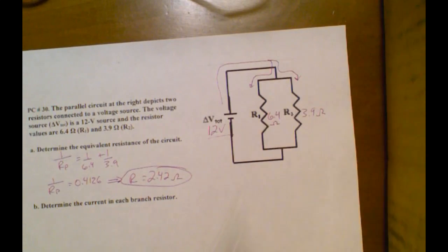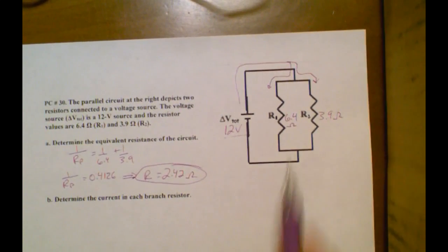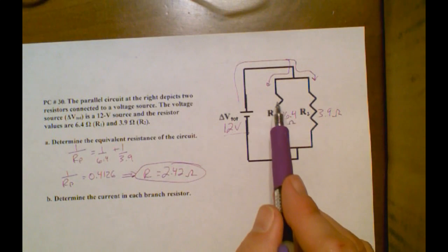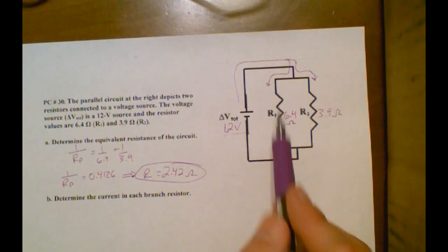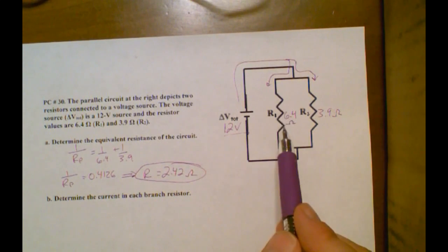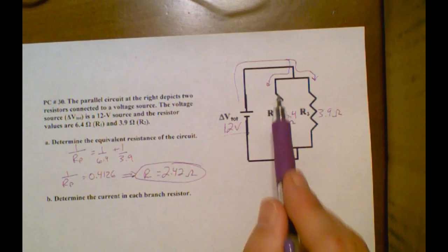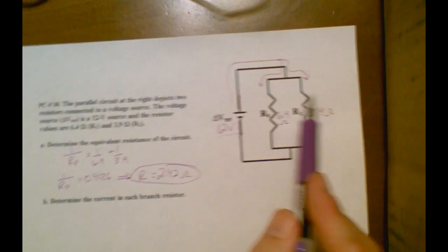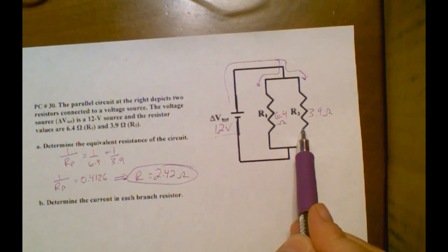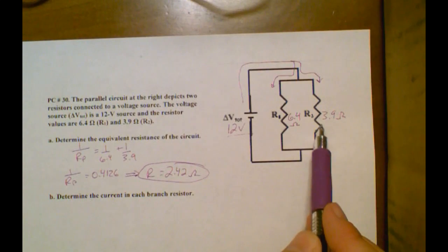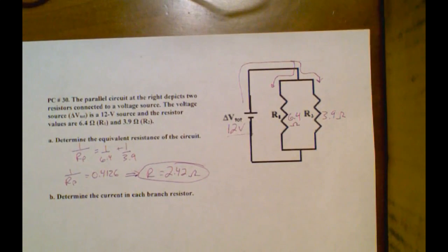A single charge would not go through both. So that means that this is the only spot on the circuit for the charges that take this path where there's resistance, and that's the only spot they'd use voltage up to overcome that resistance. So this would be 12 volts across here, also 12 volts across here. So no matter which path a charge would take, it would use up all 12 volts across the resistor.